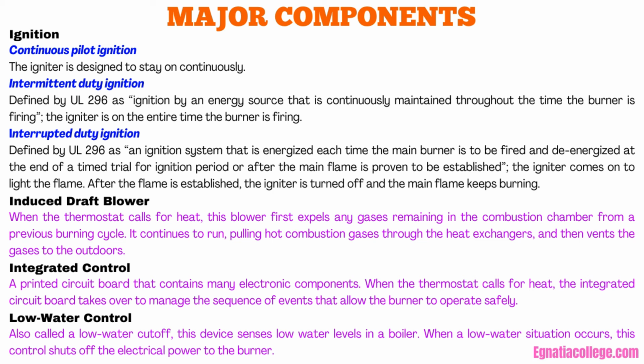Induced draft blower. When the thermostat calls for heat, this blower first expels any gases remaining in the combustion chamber from a previous burning cycle. It continues to run, pulling hot combustion gases through the heat exchangers, and then vents the gases to the outdoors.